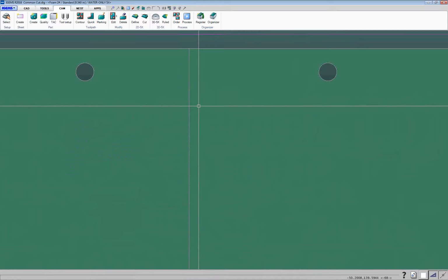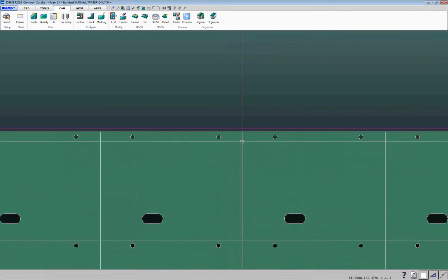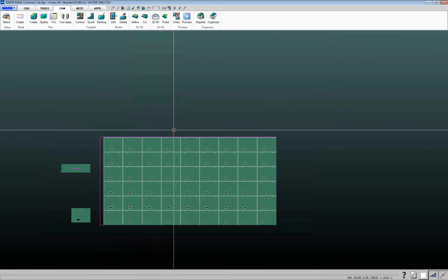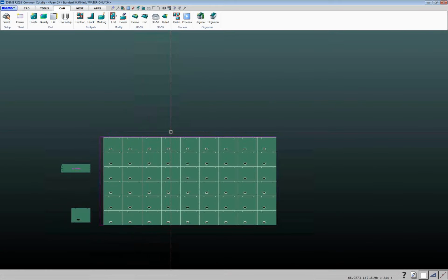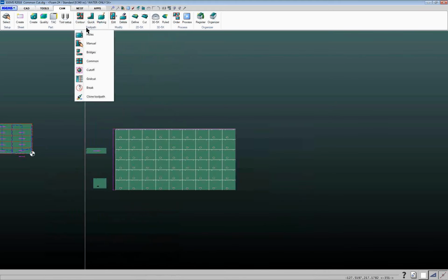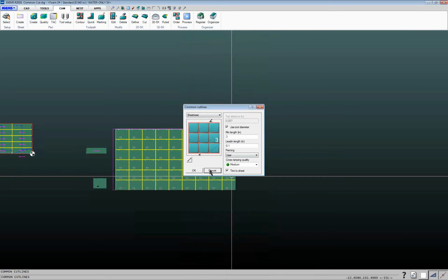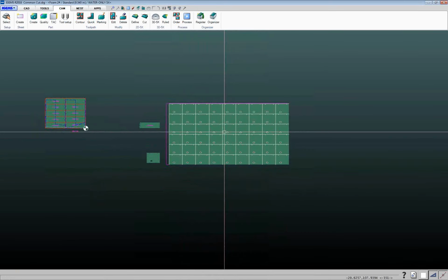So basically what it did there was, rather than creating a sort of tool path, it just makes the CAD lines for that common tool path. And then, as I say, you could copy that, make a DXF file if you want to bring it into another CAD package or something. I said I haven't really found myself a lot of use for that, but that is available. That's what that lines option is there. So that's the common cut command.